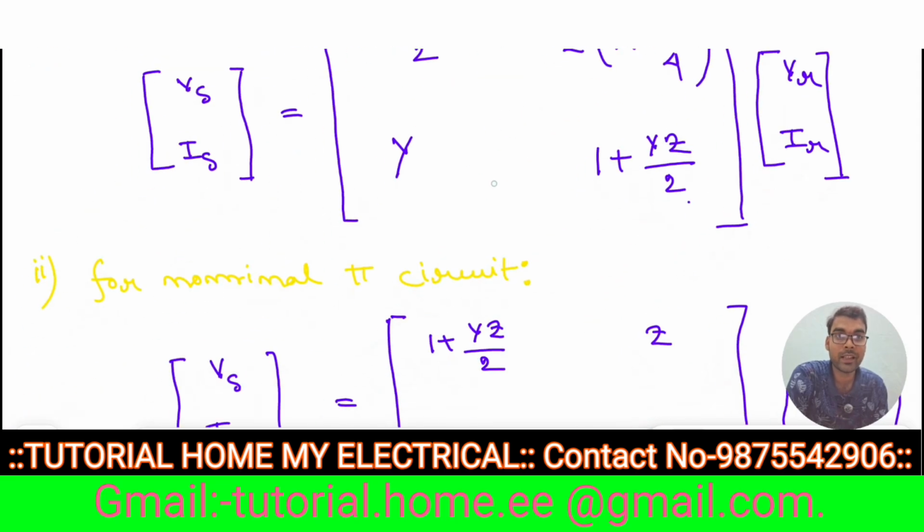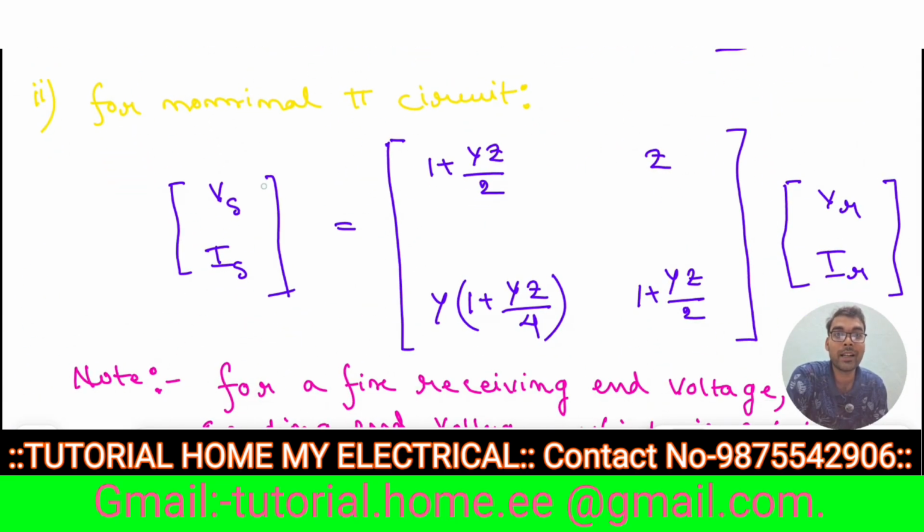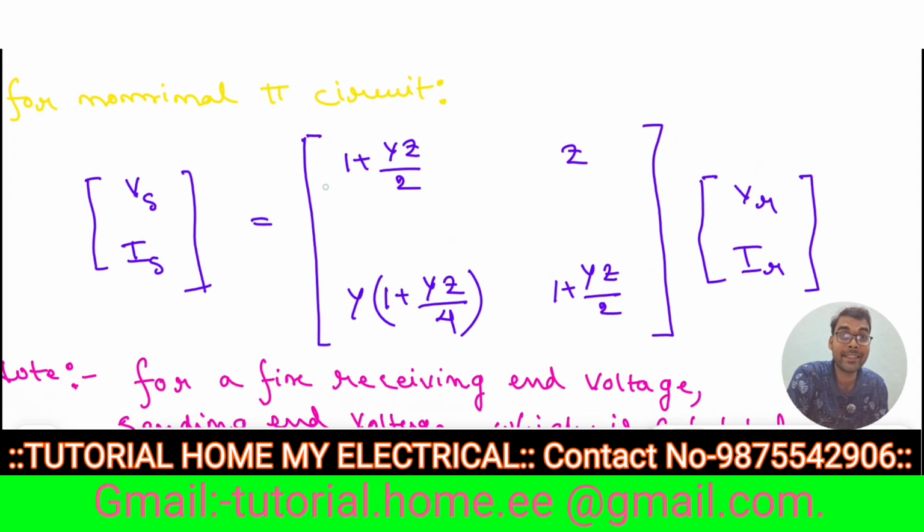Okay. Now we have to go for nominal pi circuit. For nominal pi circuit, A is 1 plus YZ by 2, B is Z, C is Y into 1 plus YZ by 4, and D is 1 plus YZ by 2.